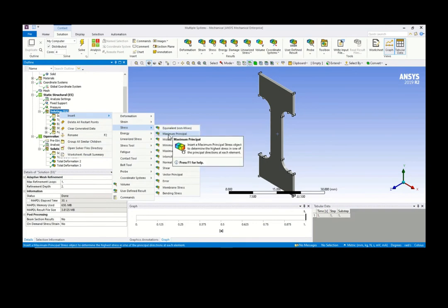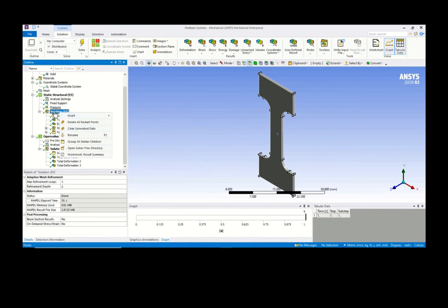Of course, you can use maximum principal stress, which is your sigma 1, or middle sigma 2, sigma 3. Then you have maximum shear stress, MSS. If you are using MSS, then this stress is used to calculate your static failures, maximum shear. Here we are using equivalent stress, because later on we want to use the so-called DE theory. Next is calling out the stress tool.